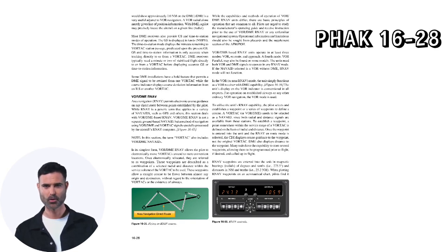To establish a waypoint, a point somewhere within the service range of a VOR-TAC is defined on the basis of radial and distance. Once the waypoint is entered into the unit and the RNAV en route mode is selected, the CDI displays course guidance to the waypoint, not the original VOR-TAC. DME also displays distance to the waypoint.